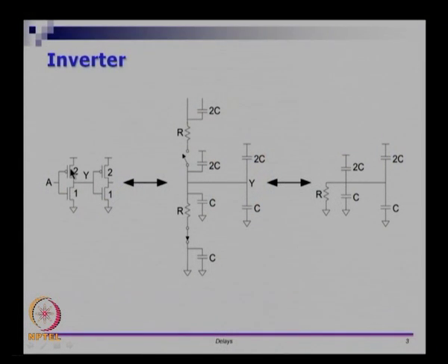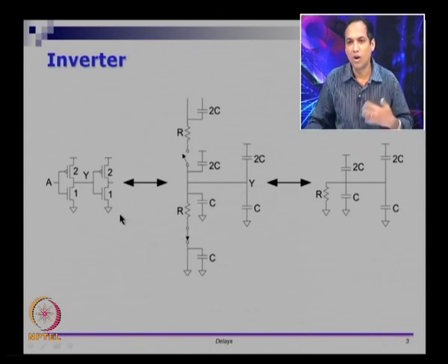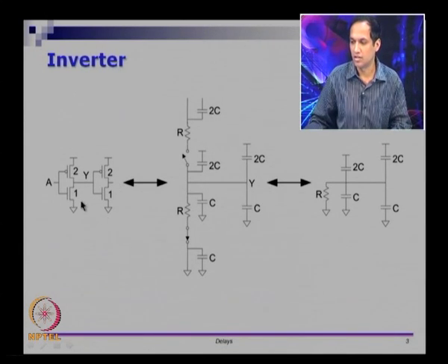Let us take a basic inverter. So, the basic inverter is here. Let us say I take this inverter and connect it to another inverter. So, Y is A bar and let us say Z is Y bar. So, Z is actually A. This is just to show you electrical parameters; this is not how to design a buffer, I am just showing you how to calculate various electrical parameters. I have this PMOS device here. Instead of a PMOS device, I will put the equivalent circuit here.